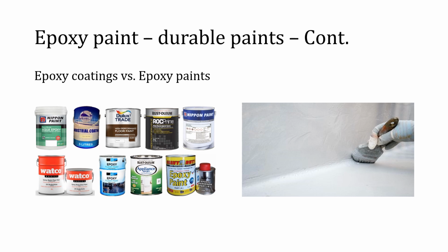Epoxy paints shield the substrate or floor from damage, especially from hidden chemicals. It is perfect for any household area where chemicals, heat, and other materials may be used. The acrylic formula can allow for customization in coloring, and this type of epoxy dries like regular paint. The epoxy component is attributed to the paint's resistance to the chemical stains on the floor like gasoline or oil, so it is often used on garage or workroom floors. Epoxy paint can cost almost $30 per gallon, which is enough to cover a few hundred square feet of space.